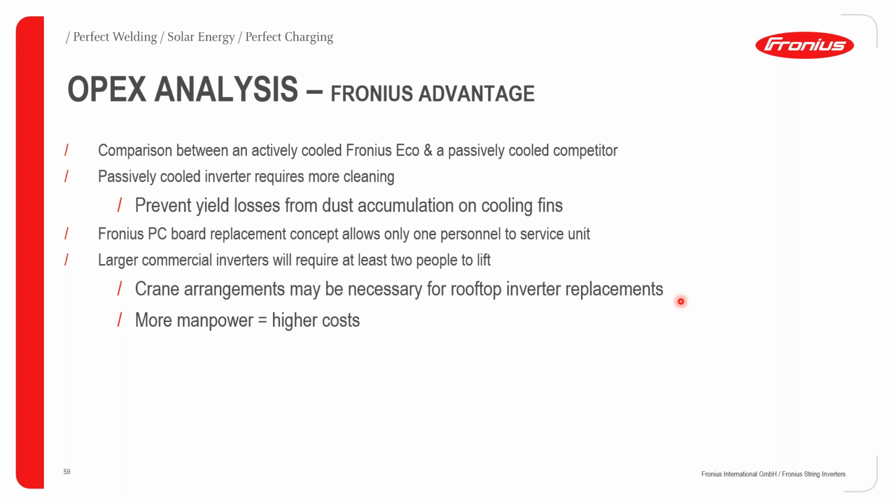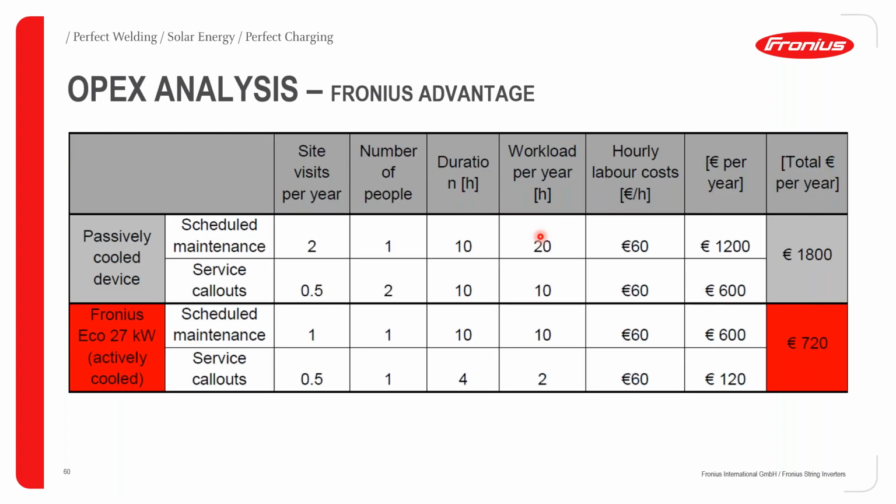For larger commercial inverters, we require at least 2 people if you have to bring down the entire inverter without the service concept of PC board replacement. And this might also require, if the system is roof mounted, crane arrangements to be made to bring the inverter from the roof, as well as to put a new inverter back on the roof. So this simply means that the more manpower you have, the higher the costs you're going to be looking at as far as Opex is concerned.